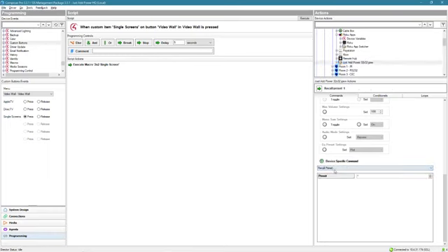You can use the switch multiple outputs, and we would do input 1 to output 4, input 2 to output 5, input 3 to output 6, and input 4 to output 7. So that at least gives us 4 different sources on the 4 TVs when we go to single screen. You can set those to whatever you'd like. But that's how you both build and break down a video wall through Just Add Power.